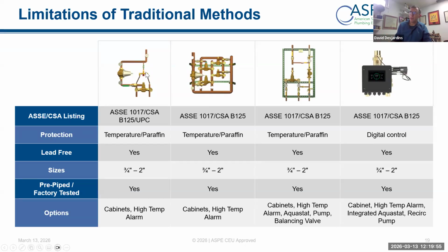So you can kind of see over on the left-hand side, there's a little guy here and a bigger one. And in between is this PRV, pressure reducing valve. So that's kind of a staging device. A lot of little flow goes through this valve. As you get more flow and the pressure starts to increase, the second one goes online. Over here, you might need more than two. That's where there's 4. Most manufacturers have these rack systems.